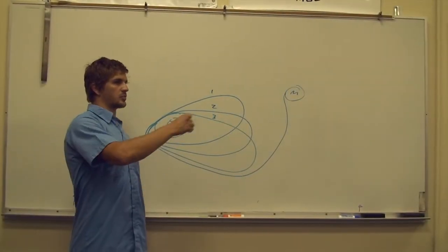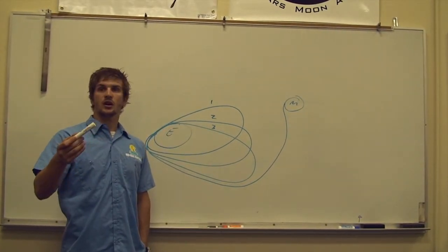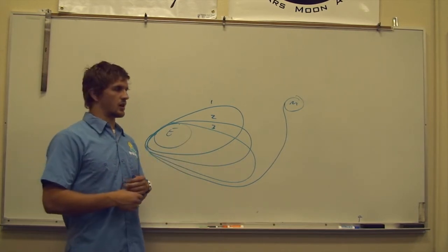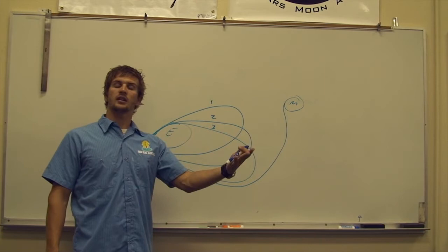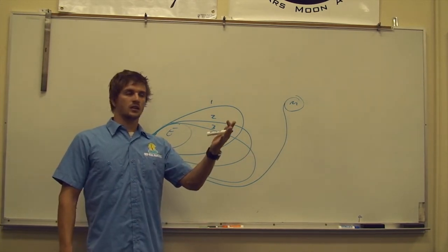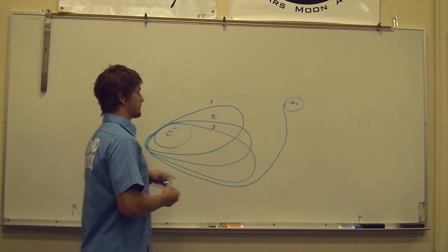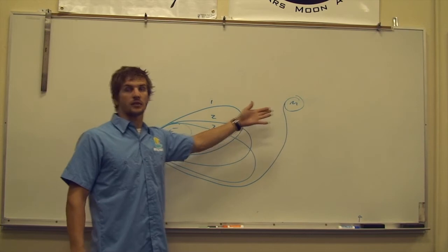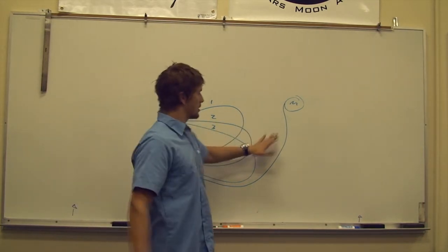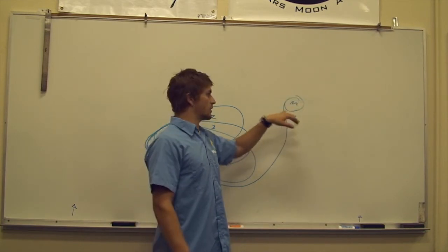Alright, once we have completed our transfer to the moon, we are going to now begin our approach to the moon. Once again, 2 methods utilized here. The most abrupt will be the direct landing. You essentially have your transfer trajectory, and you're going to target down to a landing site. Essentially what you see here is a direct method. You have targeted your site, disregard all of this, you're going to come to the moon, target your site, perform a retrograde burn, and you're on the surface.